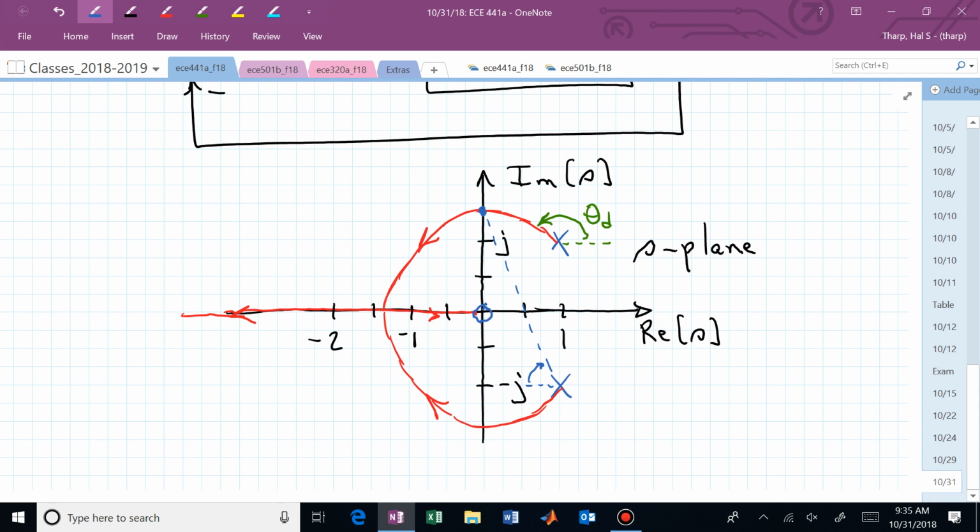I'd take that angle from 180 degrees, and that would be theta sub p1, whatever I'm labeling it. So the angle associated with this pole down here is this angle, theta p2. I calculate that as 180 degrees minus, I don't know what to call this, theta sub x.